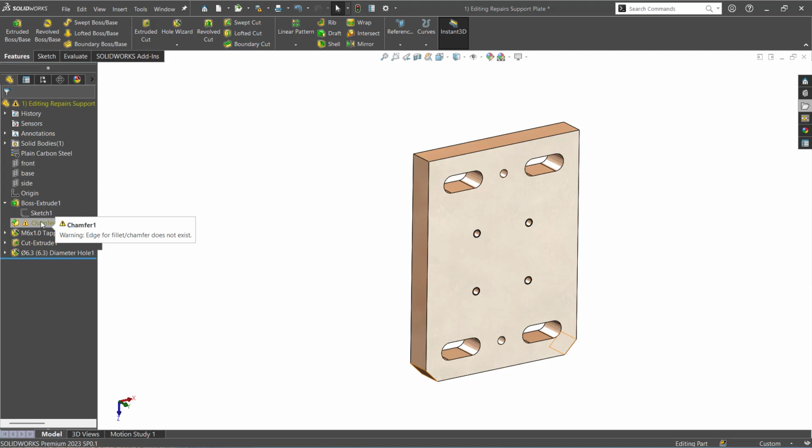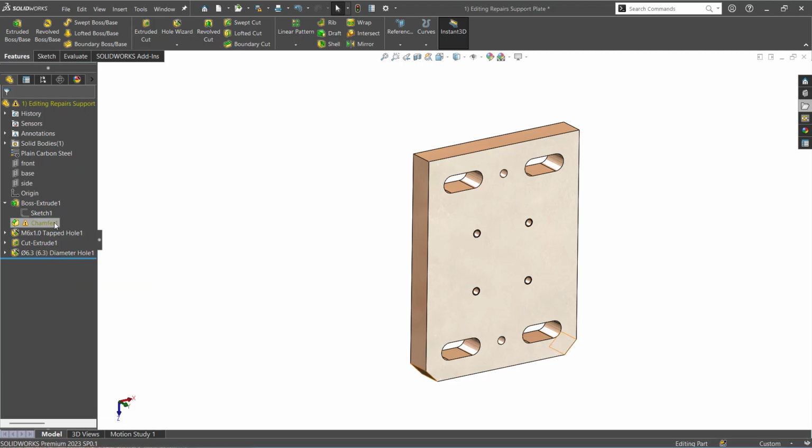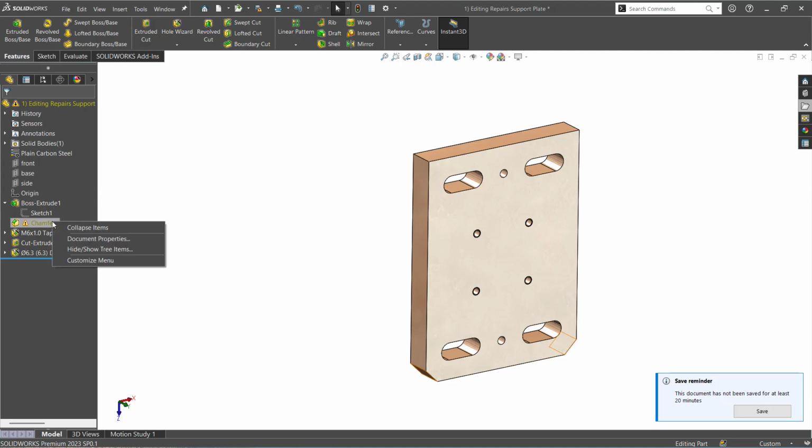First, my question is, is this particular error or warning related to a feature or a sketch? This one is definitely for a feature. Good, because fillet doesn't have any sketch requirement. What it is telling is there was an edge or edges before creating this one, so now it is not there. In short, it has been somehow removed.